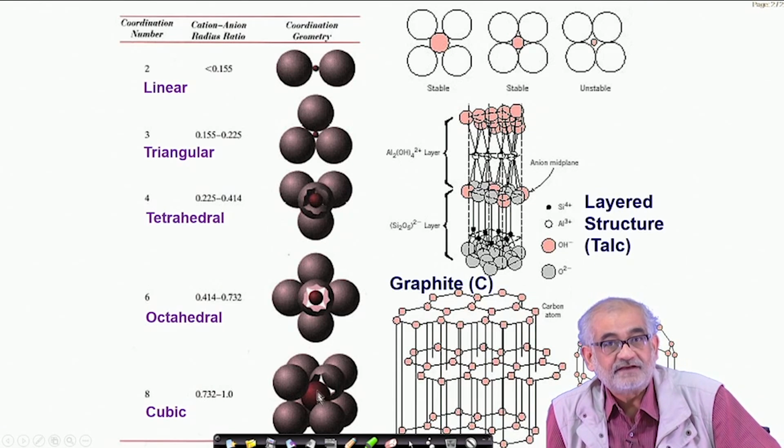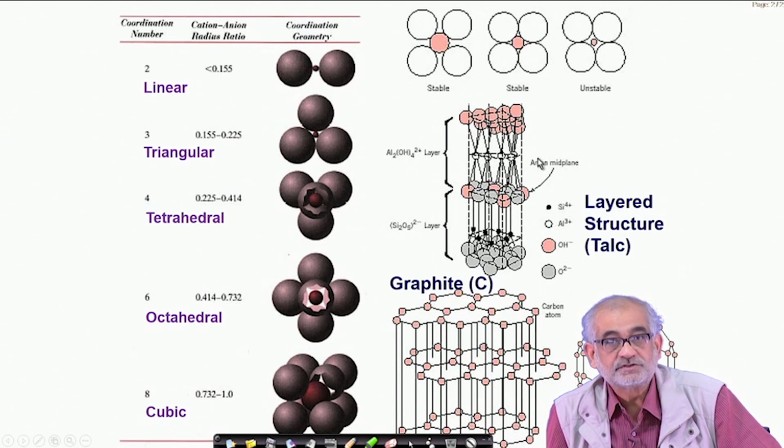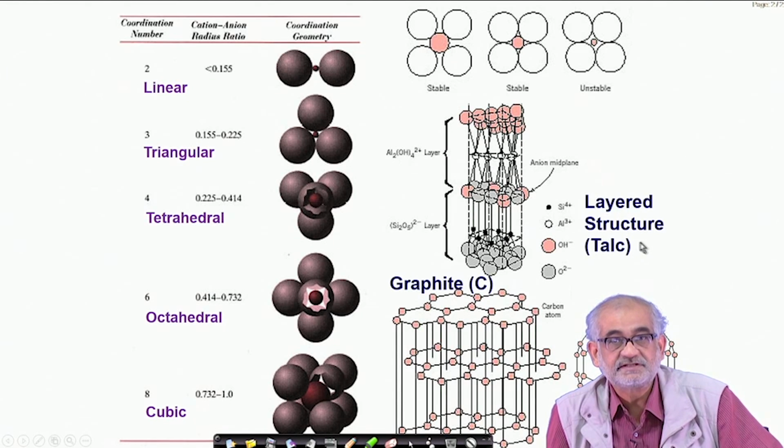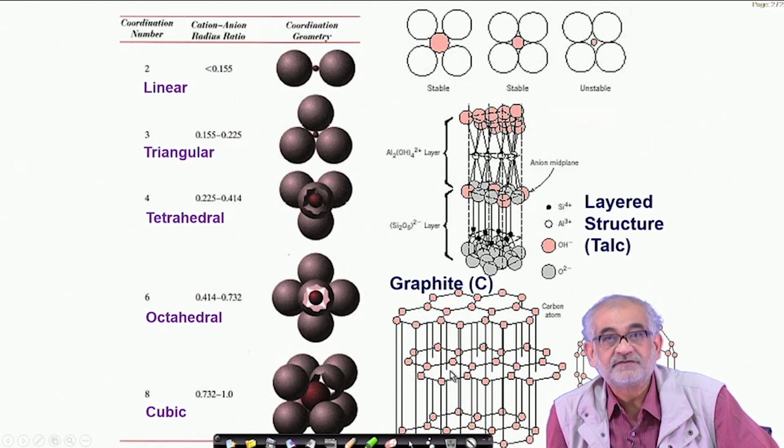So this is when you have complete crystallinity, but you may also have semi-crystallinity. For example, you can have layered structures, which we see in the natural crystal called talc, where we have these kind of layers, and in between layers we have weaker bonds, and also dissimilar species. So as a result, these kind of structures, even including graphite, actually are very good lubricants. So you see complete crystallinity in plane, but across the plane the crystallinity is not continued.